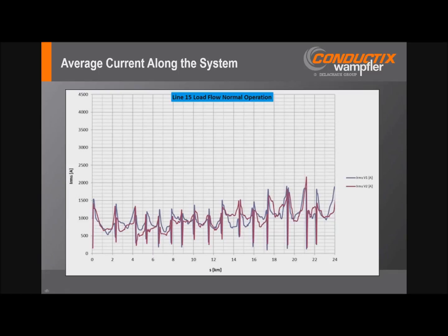How long does it take to get the system stable after commissioning? Okay, stable from a collector wear standpoint, it kind of depends on how the wear is. As I mentioned, it may be from a few hundred to several thousand kilometers. That's per a vehicle operation or shoe operation. So it depends on how many vehicles you have operating on the system, number of collectors, the headway. So essentially it comes down to number of shoe passes per day or month or week.